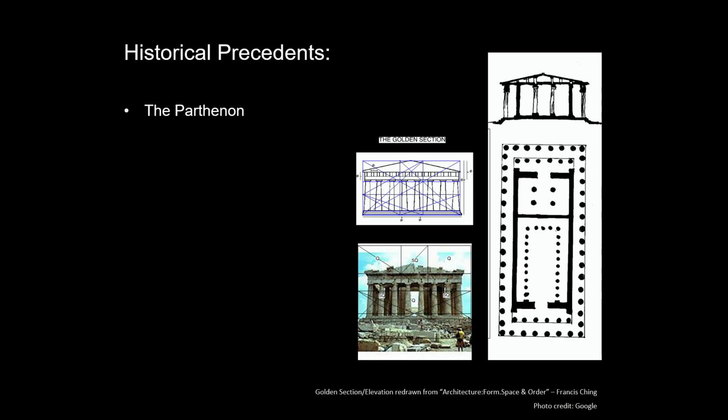It has a dense perimeter of 20% structural density, the total area of all vertical structural elements, columns, walls, braces, etc., divided by the floor area. It has a small span, and a great deal of material is brought down to the ground. There are no internally generated lateral forces due to arching trusses. The interior space, however, is very small.